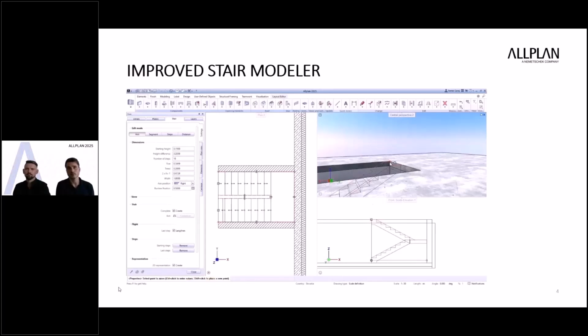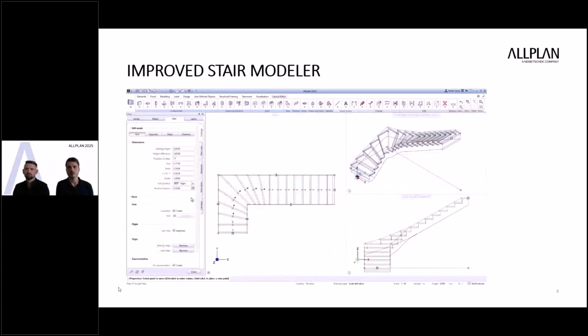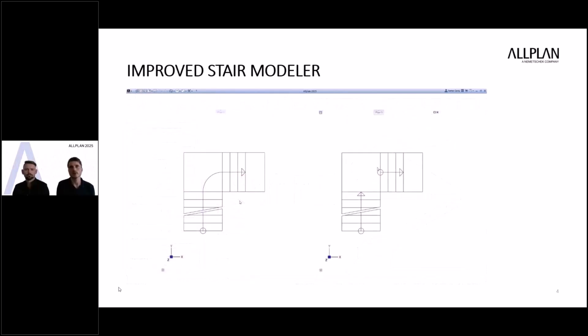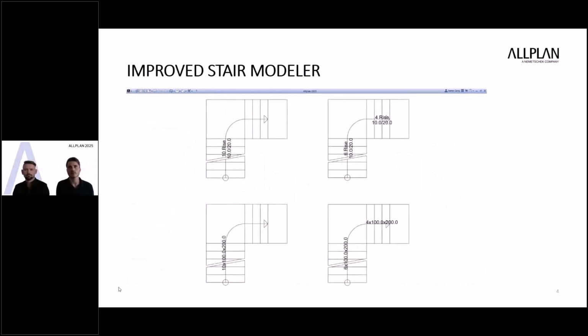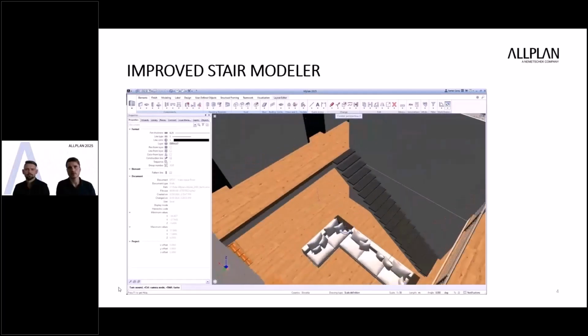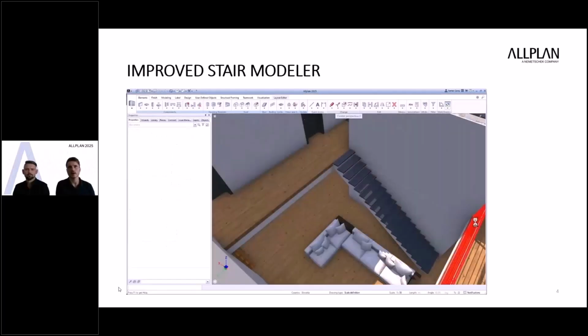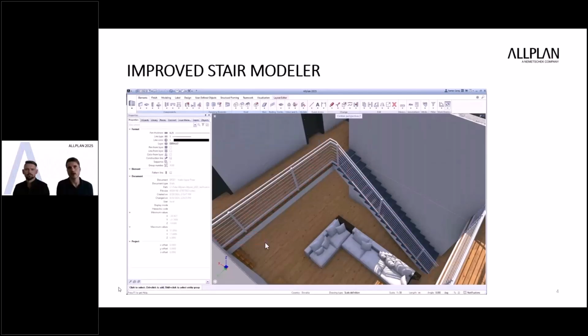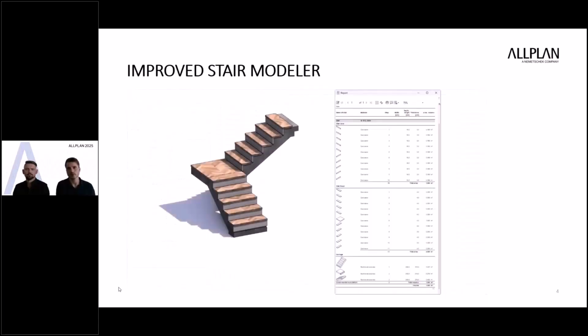Significant improvements have been made for the stair modeler, addressing country-specific requirements and facilitating more detailed quantity takeoffs with recognition of all subcomponents of the stairs. Workflow and flexibility were enhanced by a height handle, independent landing settings, and the ability to take over the stairs' regenerated path for efficient creation of the railing.